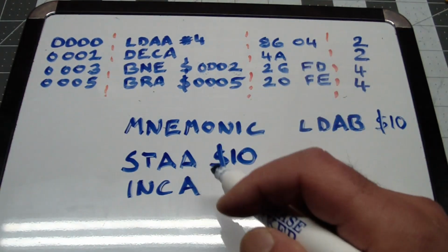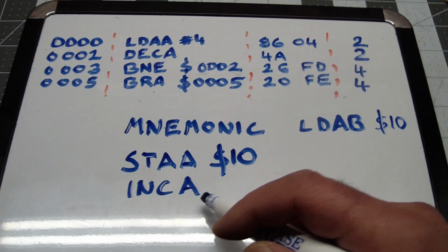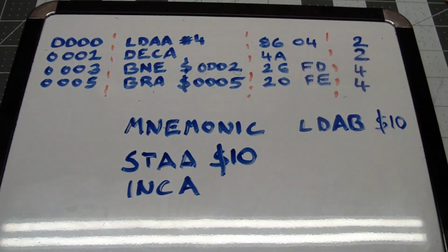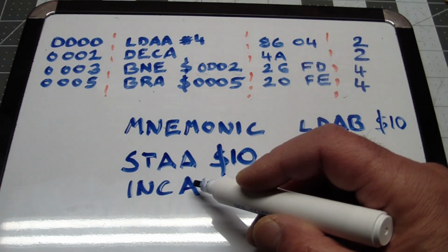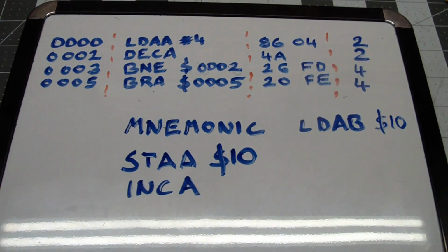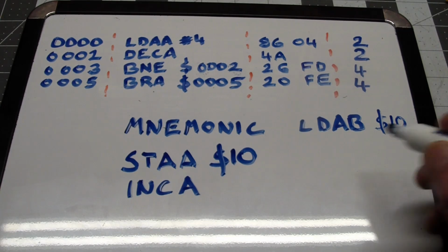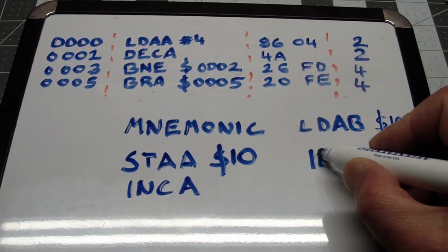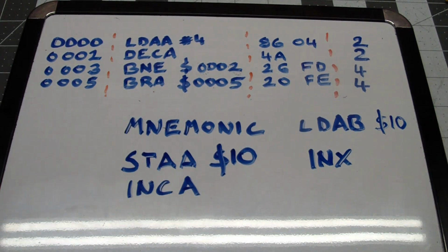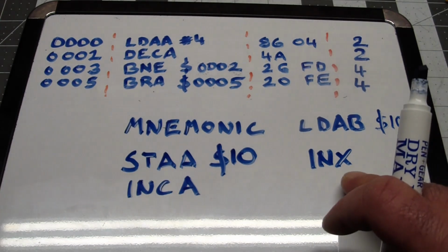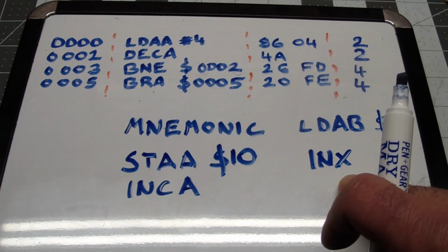So most of these instructions that have an A as the fourth letter in the mnemonic, not most, all of them exist for both A and B. And then of course we have 16-bit registers. Just to give you a taste, we can increment the X register, which is also called the index register, and that would look like this. Increment X. And the interesting thing about that, of course, is that it's a 16-bit register, so it will actually operate on the X as a 16-bit number.